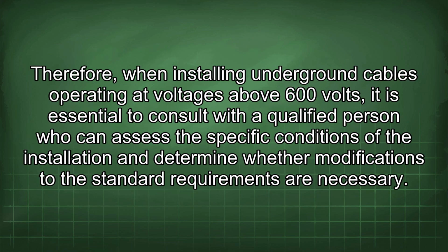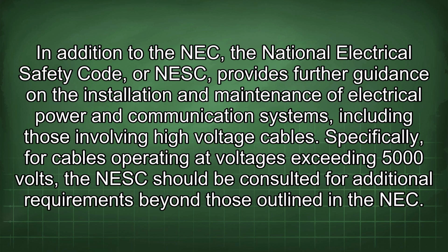Therefore, when installing underground cables operating at voltages above 600 volts, it is essential to consult with a qualified person who can assess the specific conditions of the installation and determine whether modifications to the standard requirements are necessary. In addition to the NEC, the National Electrical Safety Code, or NESC, provides further guidance on the installation and maintenance of electrical power and communication systems, including those involving high-voltage cables.